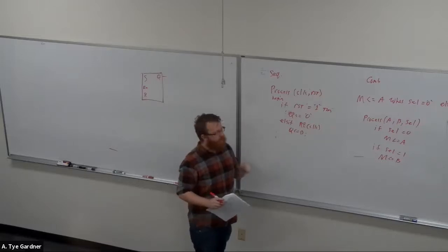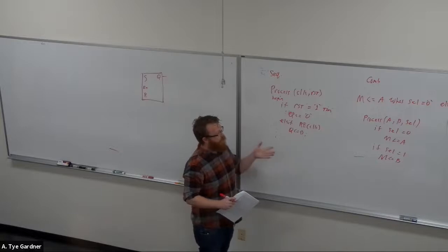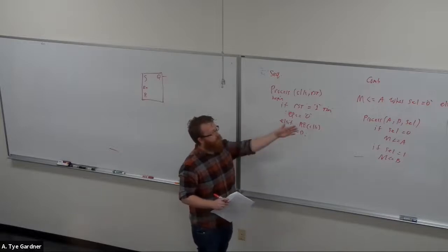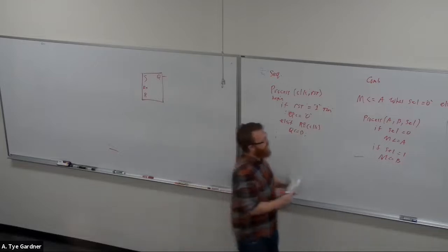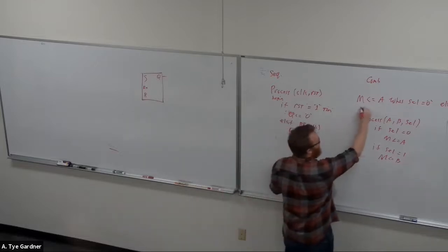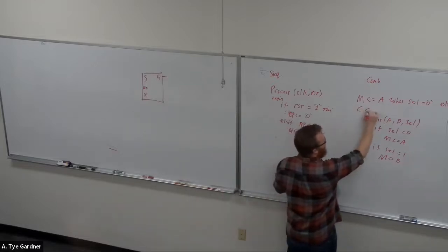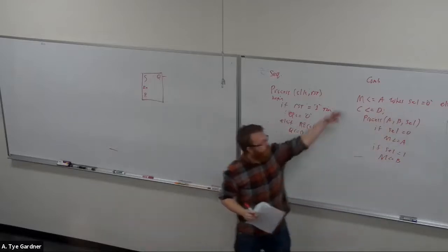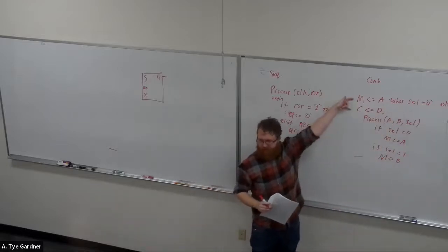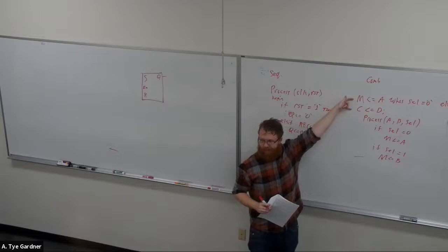Okay, what is a big difference in the way that a combinational statement executes versus a sequential? So if I have this and then I do something like another signal just does that, what order do these run in combinational logic?